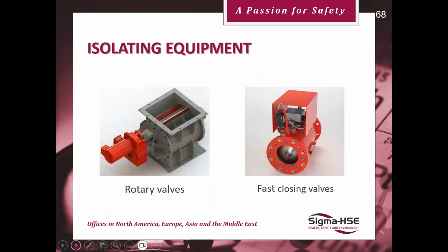Typical isolation: rotary valves, fast closing, slam shut valves, for instance. Don't forget, rotary valves will stop an explosion, but not a fire.